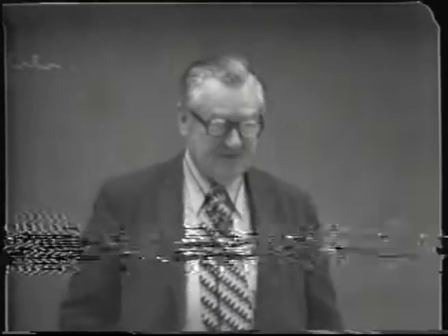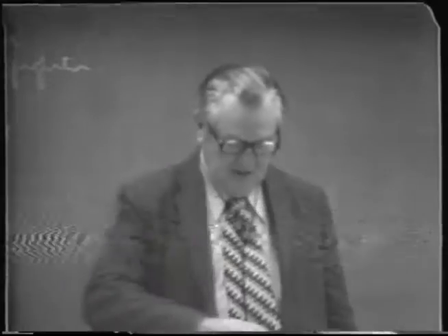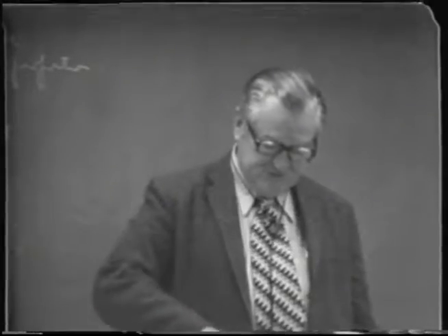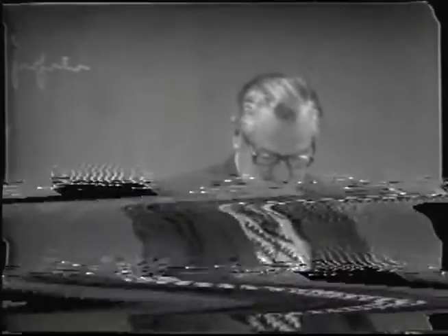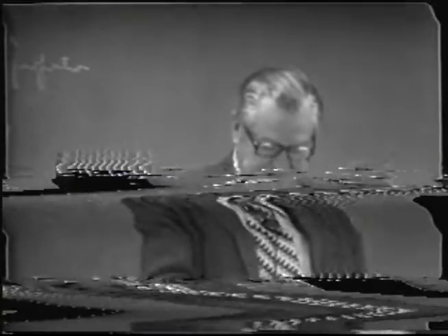The first page of that is the boiling point composition diagram, in which the overall composition expressed as isobutyl alcohol is plotted on the horizontal axis versus temperature on the vertical axis. And you see over on the left-hand corner, of course, the boiling point of water at 100 degrees centigrade.